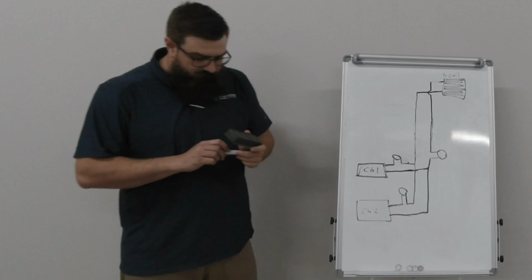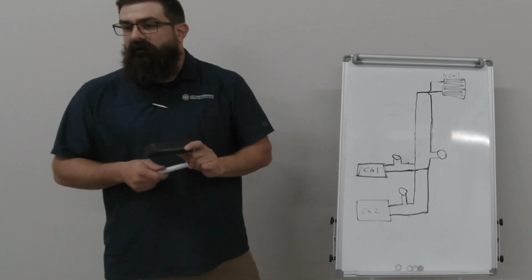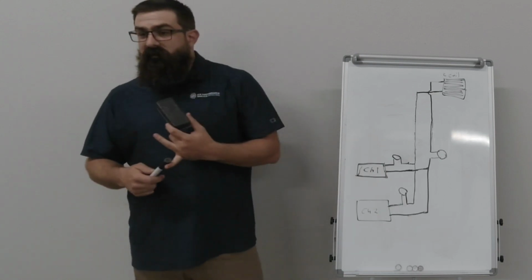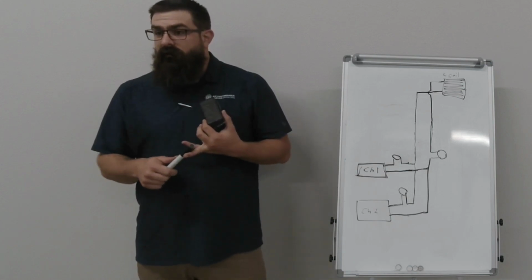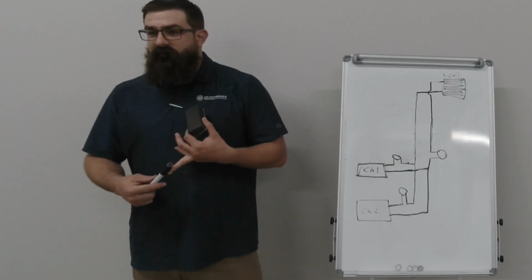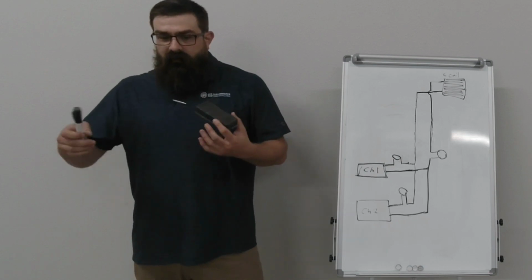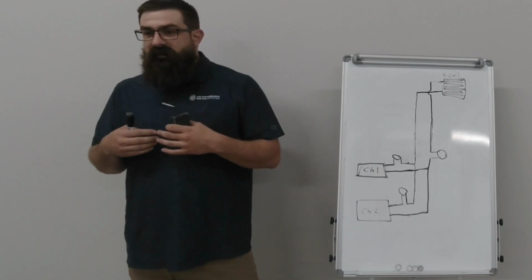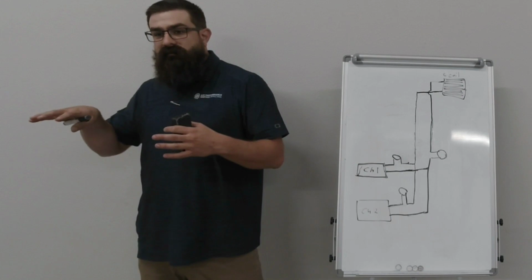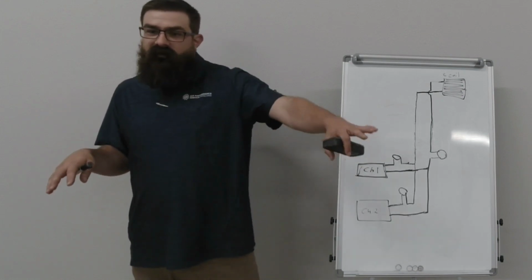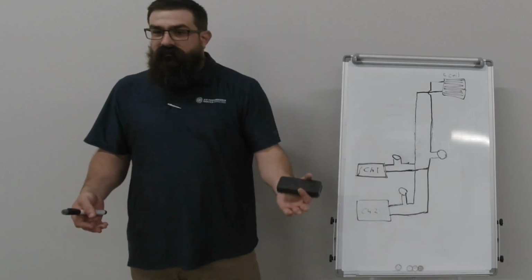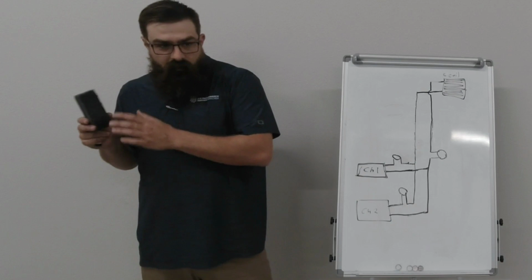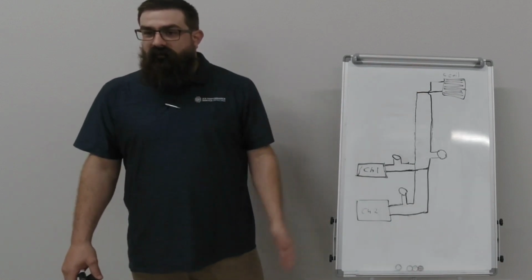to be chill water. The primary secondaries are good when you have large buildings or a chill water plant that's far away. I'll use Plaza on the Lake as an example. The chill water system is in the parking garage, which is probably 150 yards away from the building itself, and the building is 4 stories tall. So you've got a decent amount of head to push through, and all that pipe that runs underground that you have to circulate through.